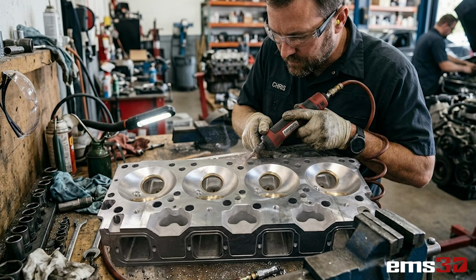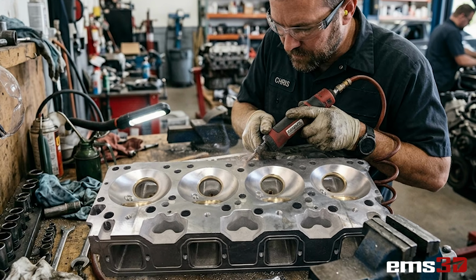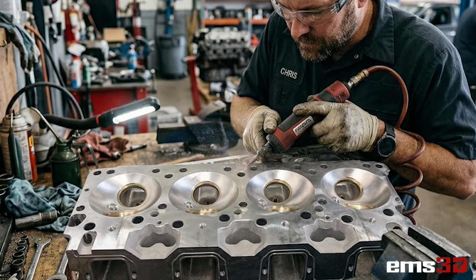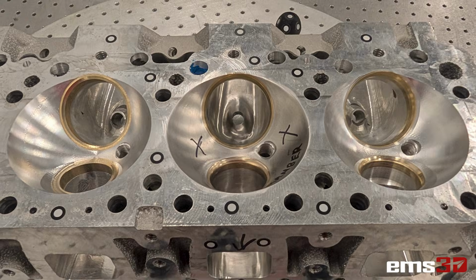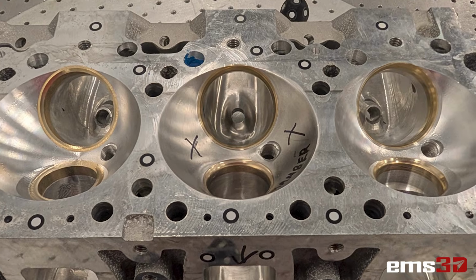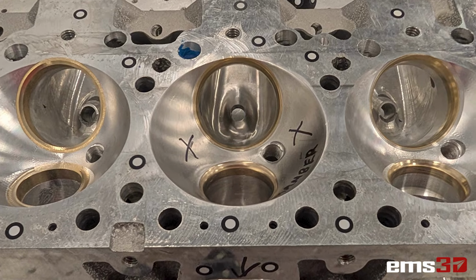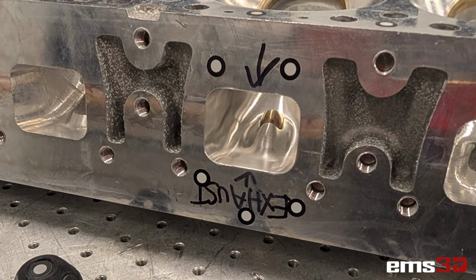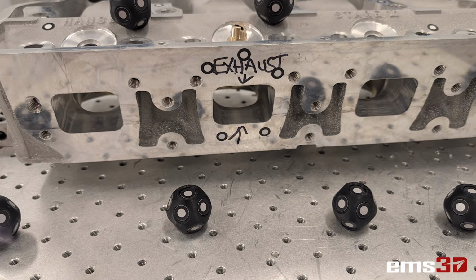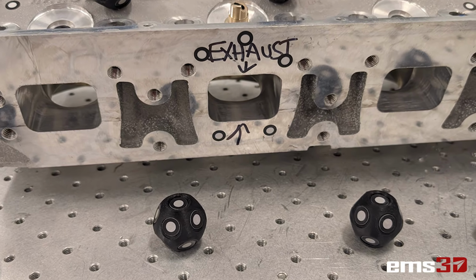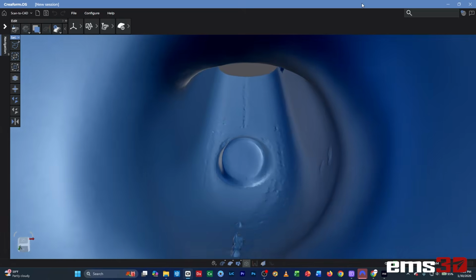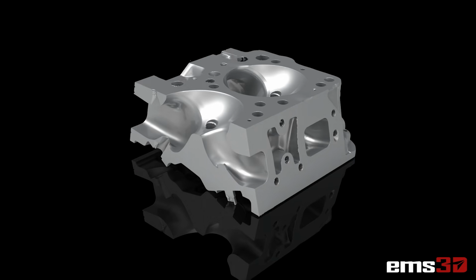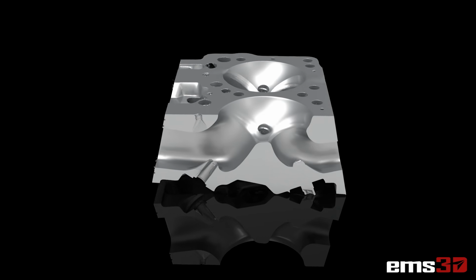But after that, they went in and ported and polished it by hand and took out even more material, and did some testing and got it to be exactly what they were looking for in terms of flow and all the other characteristics, horsepower and compression, however they come up with the right shape and design for the intake and exhaust and the actual expansion chamber.